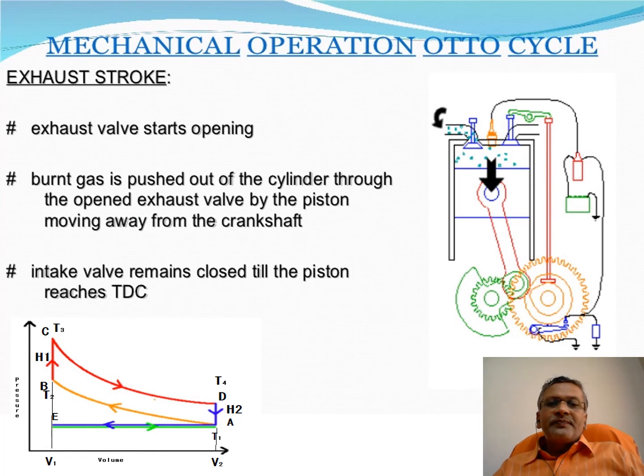Exhaust stroke. The exhaust valve starts opening. Burned gas is pushed out from the cylinder through the opened exhaust valve by the piston moving toward the crankshaft. The intake valve remains closed till the piston reaches TDC, top dead center.